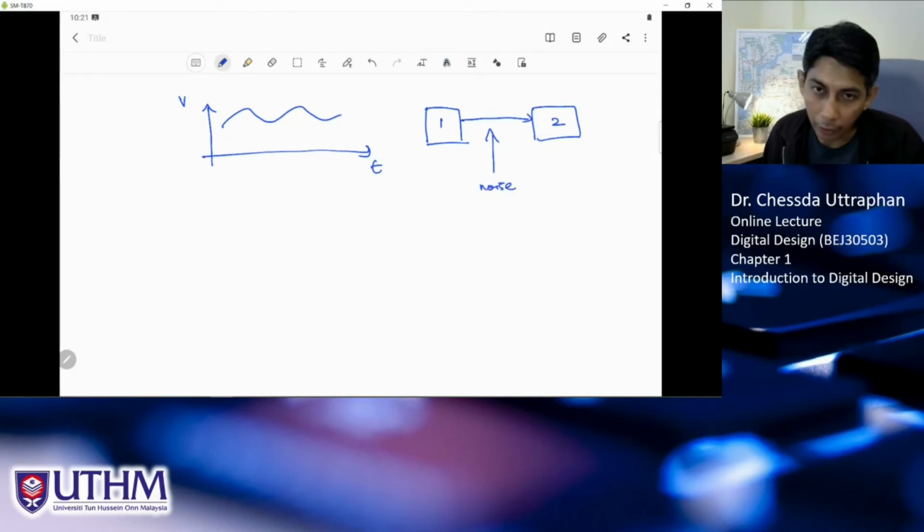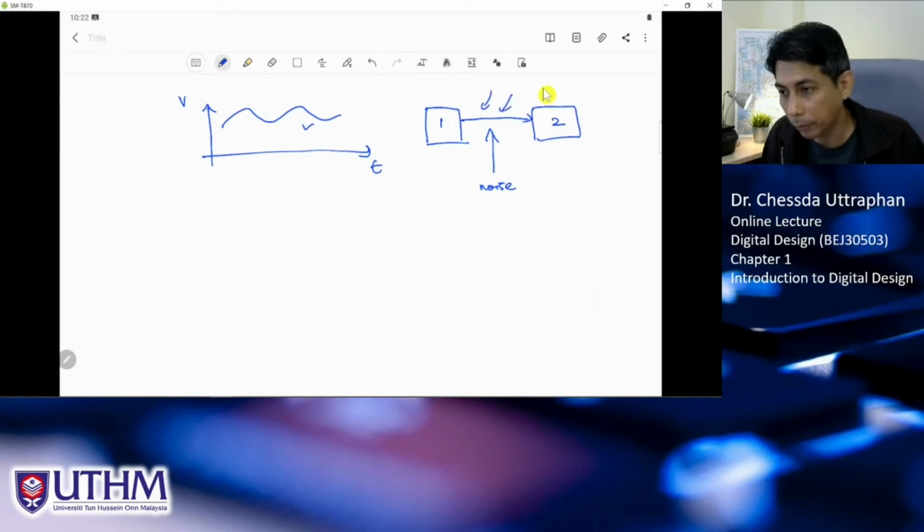Noise comes from everywhere, from the RF signal from outside, from space. It interferes with your signal here, because this wire is actually a good antenna, a conductor, so it will induce any signal that comes from space, or any other electronic devices will radiate noise to your system.